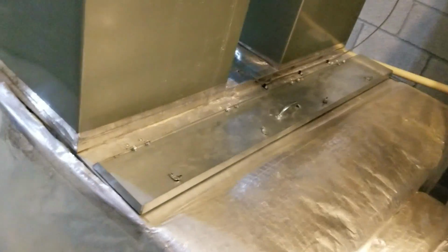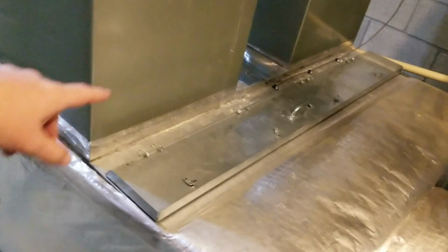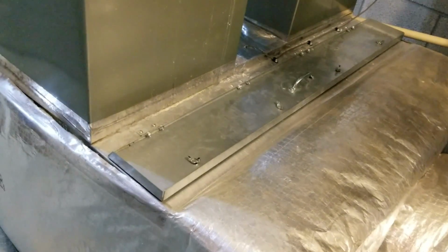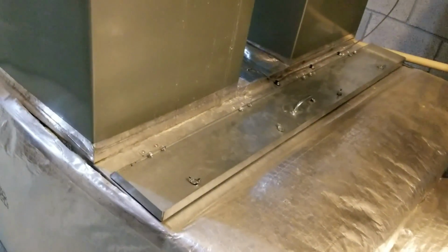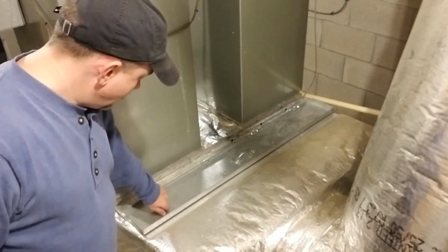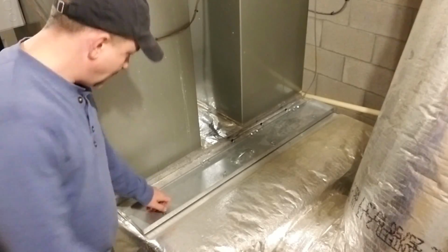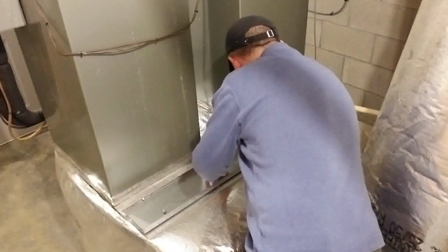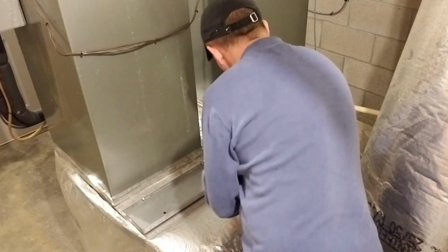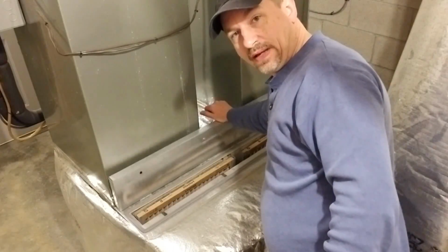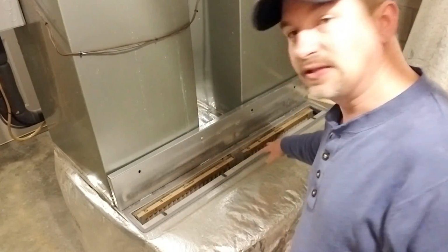So something really cool I'm going to show you is how to change the filters, because when I designed this box, I put the filters here. The filters aren't upstairs in the grates in the wall. They're here, so it makes them easy to change all in one place. I'll show you. So there's actually 4 wing nuts right in here that you take loose. I call them wing nuts, but they're actually wing bolts. So anyway, you take those 4 out, and then you can actually just lift this up, like you see here. And it gives you access to the inside.